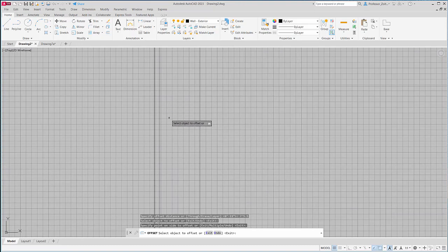Excellent. So what about the next wall that's beside it? What are the interior walls? Well, when I'm looking at this, all the interior walls to the right of that are 4.5 inches. All right, offset 4.5, enter. Notice no inch mark. Once again, it's the default setting. There it is. Great, that creates that wall.